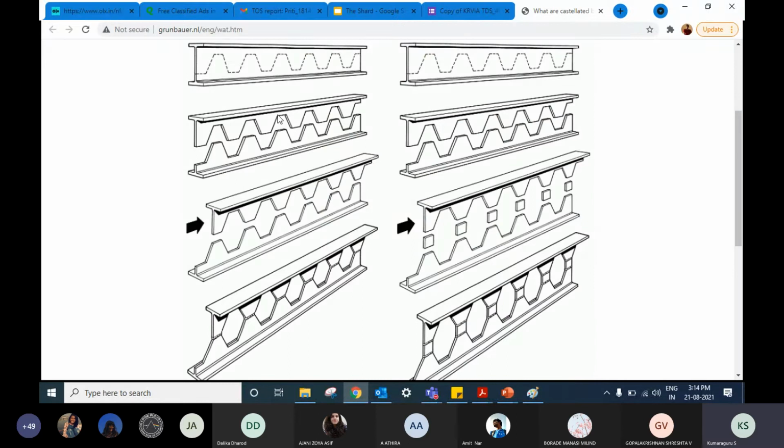It is something like this. What happens is they cut across the entire beam in a particular section. It could be a hexagonal section. Okay, they want to make a hexagonal section. What they do is they cut a hat-section-like profile throughout, and they detach these two parts, move them a little bit, and make one sit on top of the other, and again build it. There's this cutting, moving, attaching, and building.